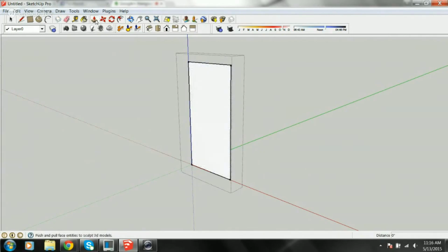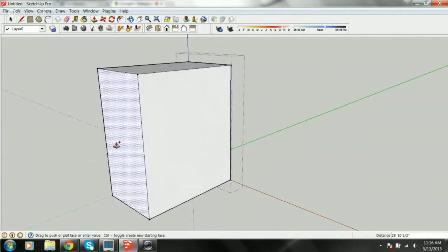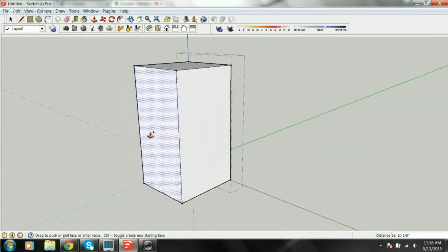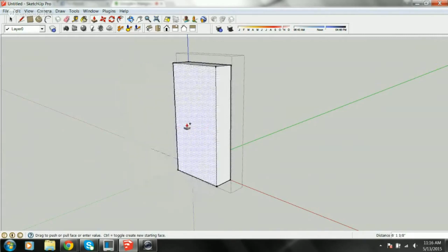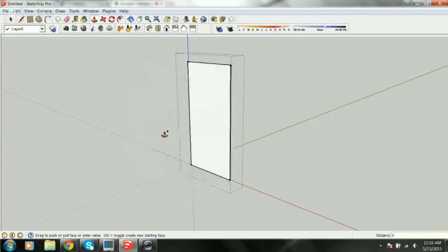Okay. I've come up here, I've selected the extrude button, push pull. You see, I haven't clicked anything. I just highlight the face because I'm within the group. Okay. Now I hit control. You see that little plus pop up? You need to do that. Because if you don't do that, what's going to happen is when I click on this face, hold the button down, and pull it toward me, and then I keep the button held down, in the bottom right-hand corner, I have that distance button again. Okay. I'm just going to hit 3, enter.